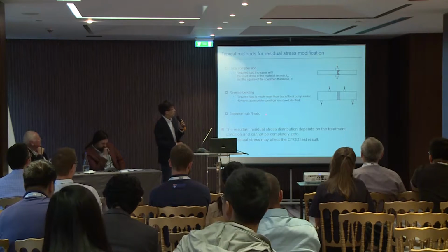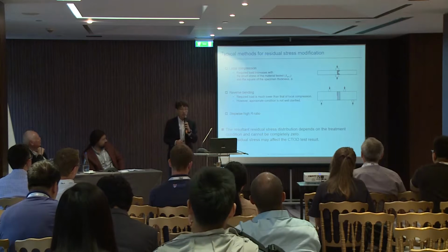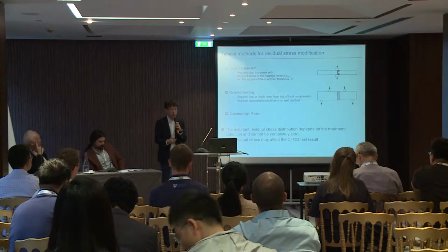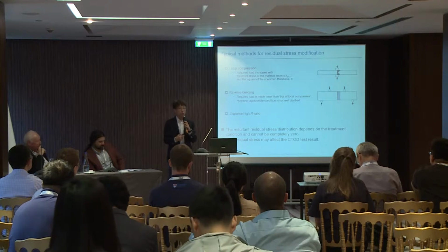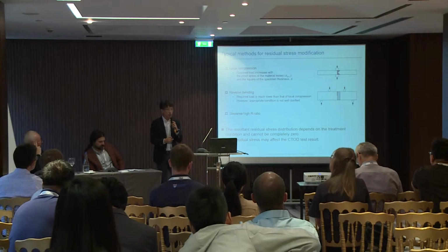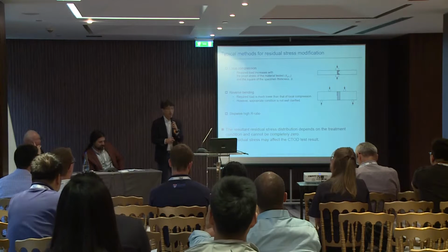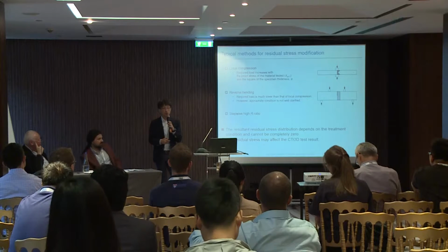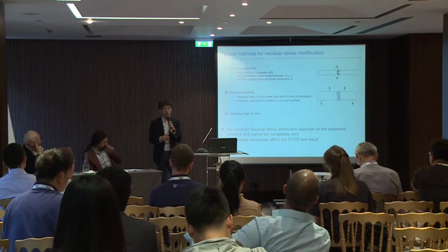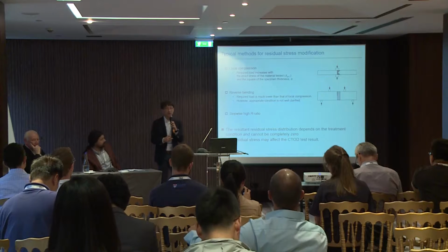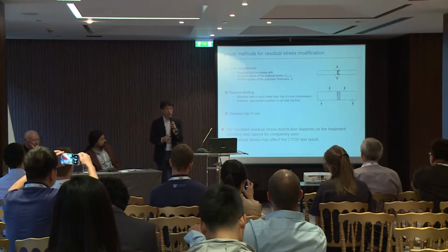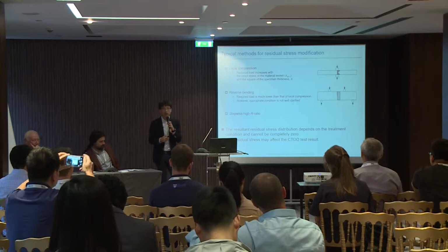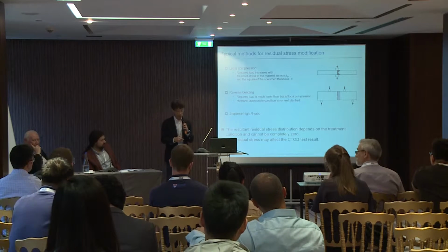So this slide shows the typical method to modify the residual stress distribution caused by welding. However, even after this treatment, the resultant residual stress distribution depends on the treatment condition and cannot be completely zero. So the residual stress may affect the CTOD testing result.